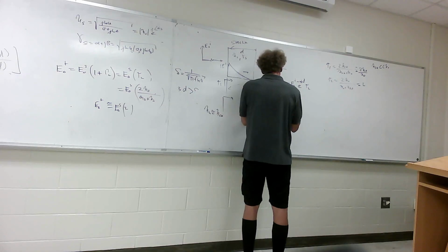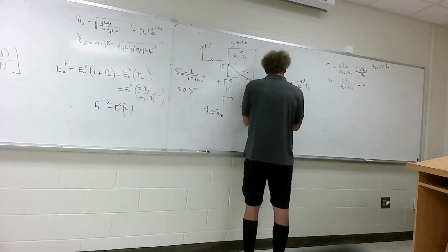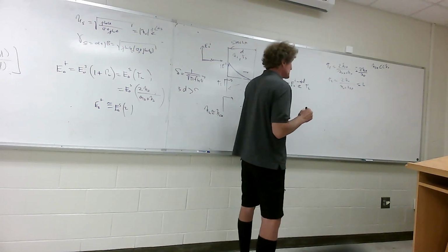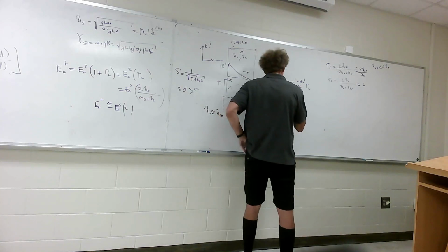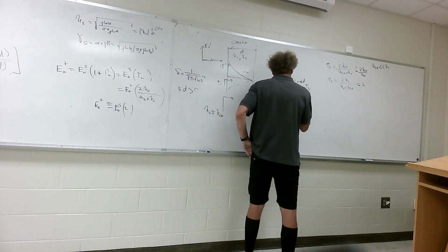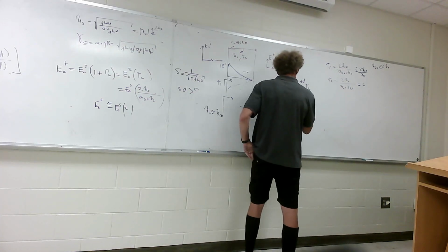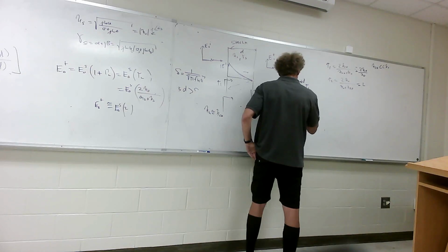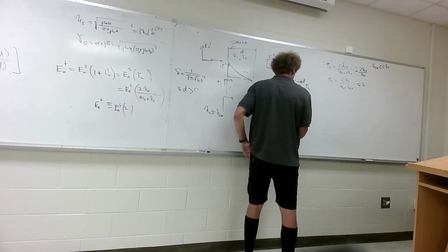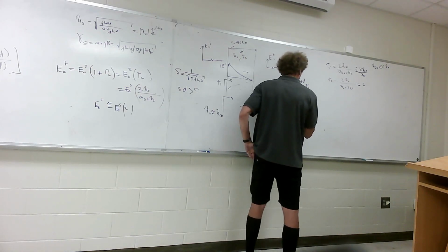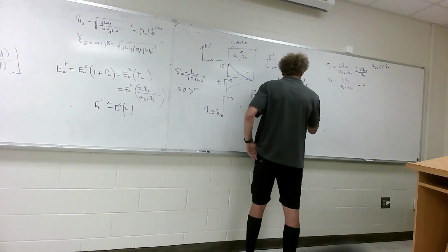When we look at the transmitted electric field's magnitude, that's the transmission coefficient, which is approximately 2 times eta of the shield over eta naught. And then it's times e to the minus alpha of the shield times d. Alpha is just the real part of gamma. And then it's times tau 2, which is about 2.